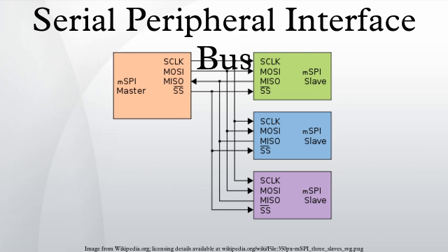As in the standard SPI, the beginning of transmission is marked by the activation of the SS line low and the end is marked by its return to high. MSPI requires the bus master to issue a slave address as the mandatory first word in every transmission. Since all slave devices share the same SS line, the address word will be received by all of them at the same time. From that point further, only the device with the specified address will connect its MISO line to the bus and start communicating, while all other slave devices will ignore any data and wait for a new start of transmission and address.